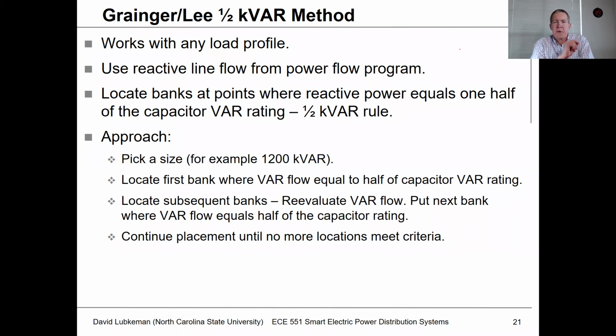So another rule that's been developed, or method I should say, is what's referred to as the half kVAR method. This is associated with Dr. Granger. Dr. John Granger is the same person who is involved in writing the 451 textbook with associate Dr. Lee. And this actually works with any load profile, so we don't have to worry about whether we have distributed load versus spot load. It works with any load profile.